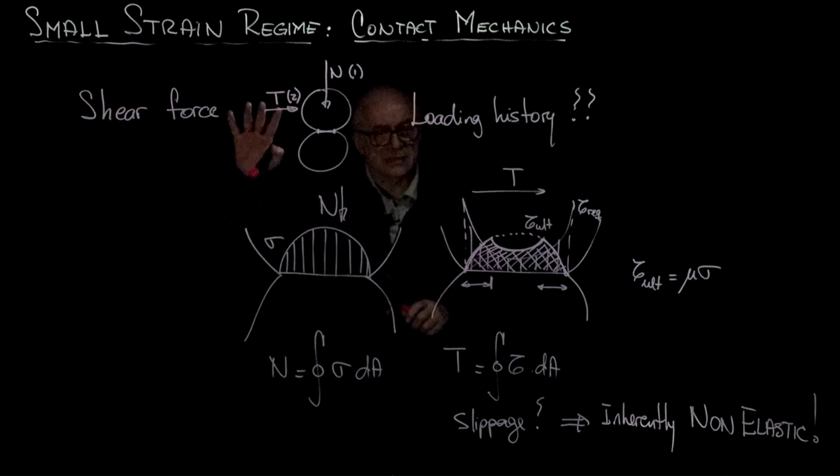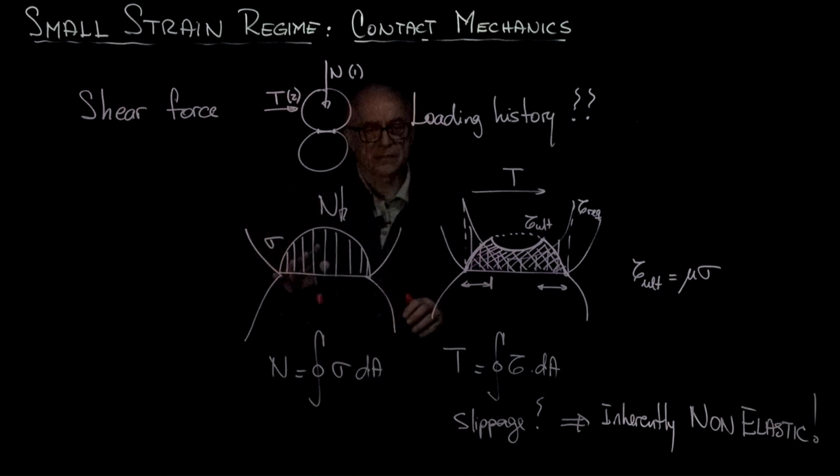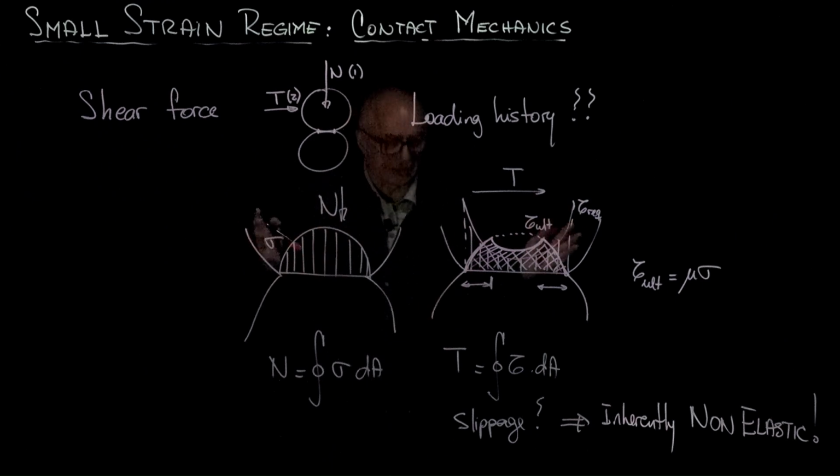From Hertz and Hertzian type behavior, all contacts under normal load, because of the stress concentrations and the nonlinearity of that behavior, the macroscale response of a soil is inherently nonlinear. Now, because there are shear forces at all contacts, then we can also conclude that the behavior of the soil is inherently non-elastic.